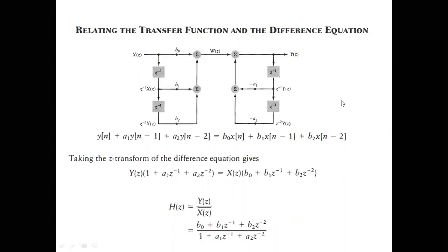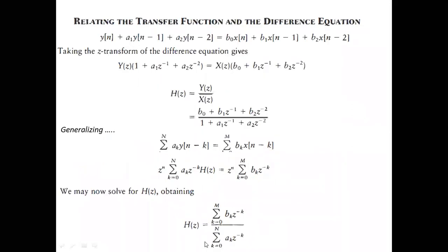So did you get this thing? You had the difference equation here. You took the Z transform. You got Y(z) and the ratio outside, and there you have H(z), the ratio Y(z) by X(z), giving you the transfer function. This is also a transfer function, whereas H(s) is also a transfer function. This is for digital circuits; that was for analog circuits. This, by the way, is a generalized method where you don't know the values, just some a and some b coefficients.